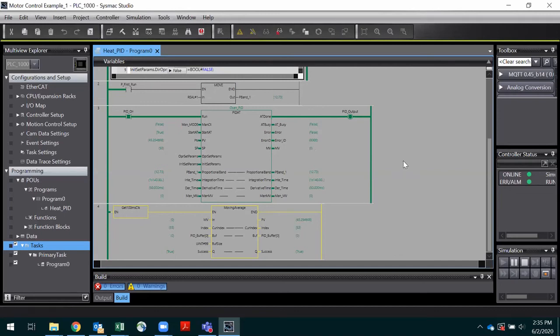So you can actually run it again if you wanted to. No, you can leave that bit on pretty much all the time. You could just toggle the auto tune bit false and then true again, and it'll redo your tuning. I assume it's still populating the array of 100 in the moving average, so that might be why it starts out jumpy.